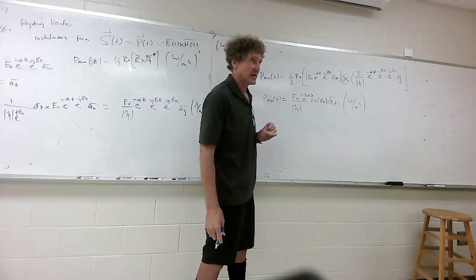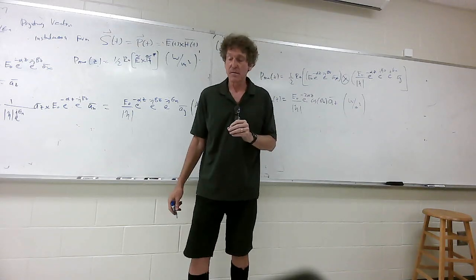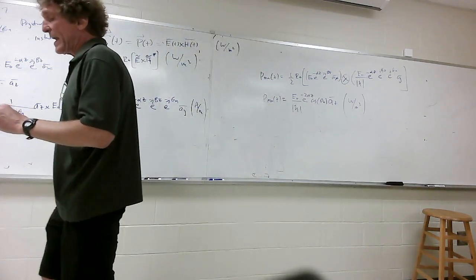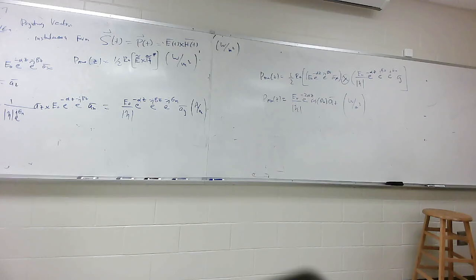cosine there. Now, for the angle of the intrinsic impedance, the largest value you can have is 45 degrees. And if it's lossless, the angle is 0. What's the cosine of 0? 1. Cosine of 45, 1 over square root of 2. So the most reduction due to that cosine term is just 1 over square root of 2, about 70%. So just keep that in mind.